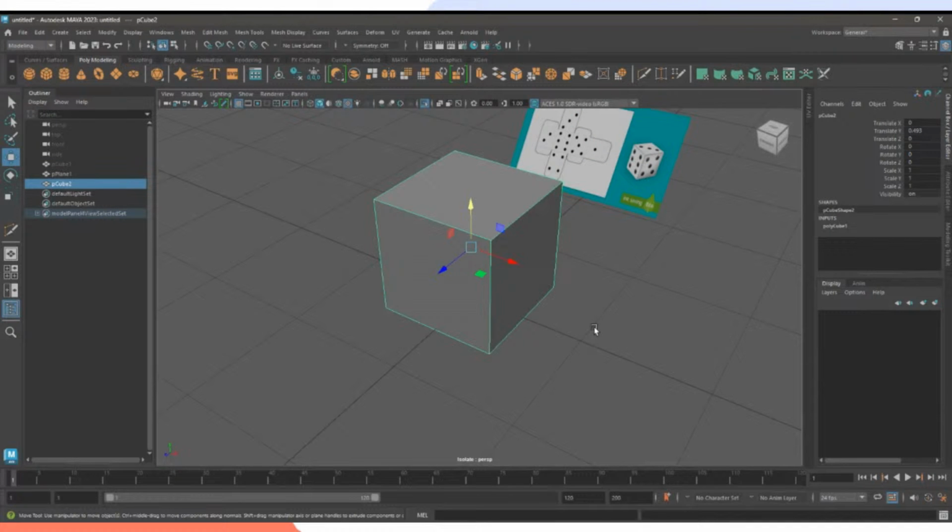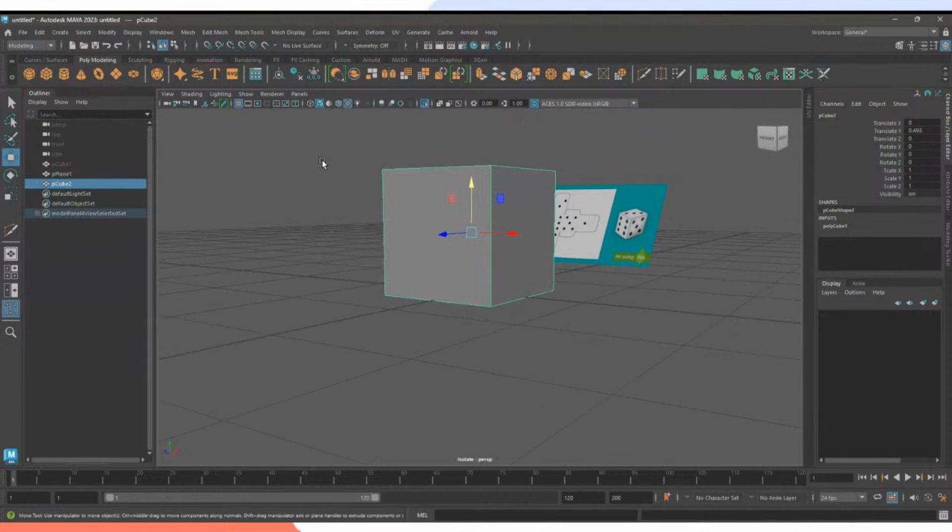One of the things you can do here is snap. Like snap to curves, snap to points, snap to projected center. We're going to snap by using snap to points, pressing the D key.